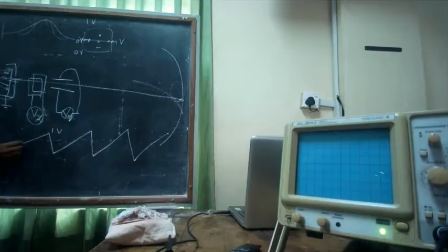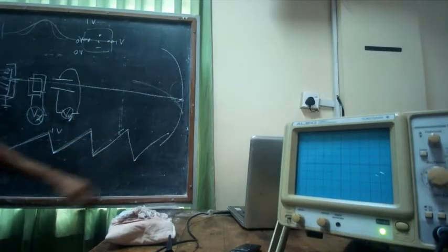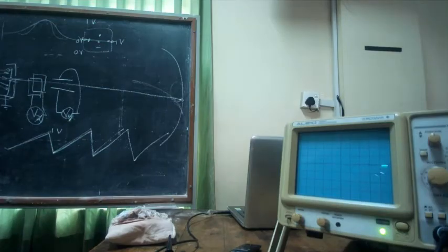So it goes from here to here, comes back, goes there, comes back, right? That's what you have. But when it comes back, do you see the signal? If I apply this particular signal, it should also show a line coming back very fast, right? Going forward slowly, coming back very fast. That's what you should see if this is what actually is happening inside.